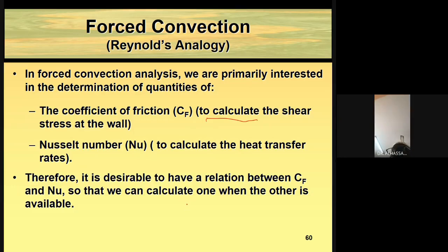Let's say we have fluid flowing across a flat plate like this. The development of the boundary layer across the flat plate is this. At this point, the velocity equals 0. The velocity will be changing gradually, 0, 2, 4, 5, 6, until it reaches a point whose velocity equals 99% of the free stream velocity. That distance is given by the velocity boundary layer.